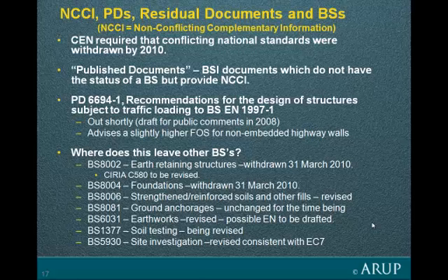CIRIA C580, which is the document on embedded retaining structures, is also listed as non-conflicting complementary information. Hopefully that will be revised. It doesn't need very much revision. Hopefully it will be revised to be entirely consistent with Eurocode 7. The Foundations Code BS 8004 is similarly withdrawn, no longer a current British standard. So if you're being required to design to current British standards for retaining structures and foundations, you have to design to Eurocodes. They are the current British standards.